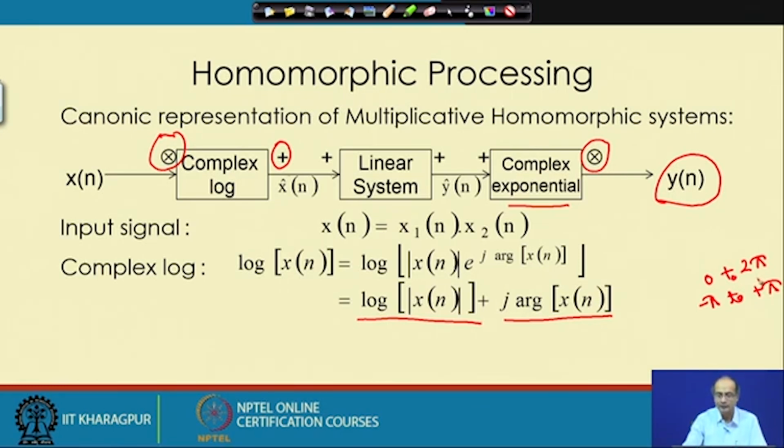Now, for that we need to understand what this phase actually means. Phase means there is a lag when we are talking about a signal where multiple components are there. For example, in the Fourier transform of a signal, we have multiple frequencies present, each one of them has some magnitude as well as a phase. What that phase means is the phase difference between them at the starting point. Each one of them, say a complex sinusoid, does not start from zero phase.